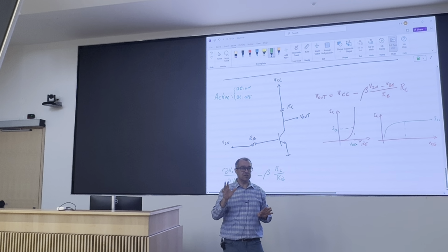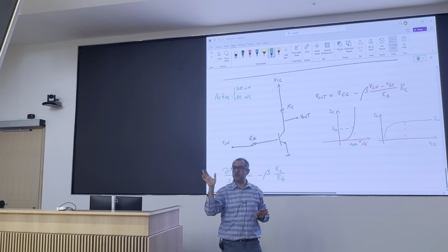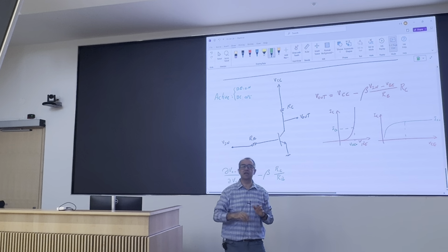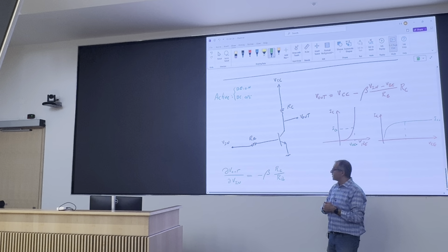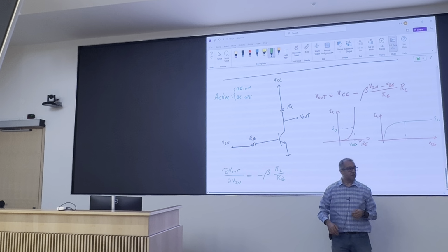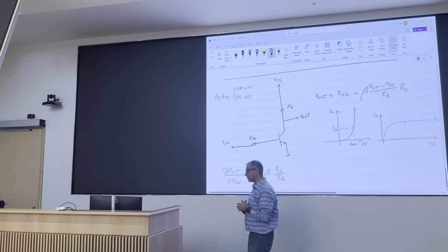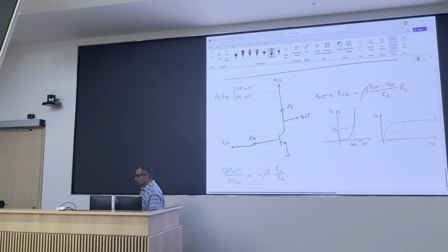There are some applications where we have to care, but for most applications, 180 degree phase shift doesn't make a difference. Right? So you have an amplifier. One transistor, and actually, that's all you really need. One transistor, a little bit of DC at the input, a little bit of DC at the power supply. Just pick a couple of resistors and you have a good amplifier.